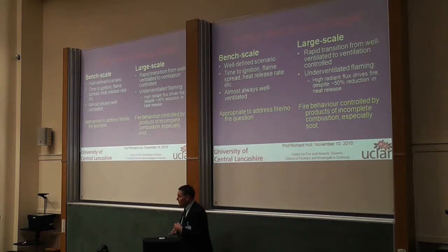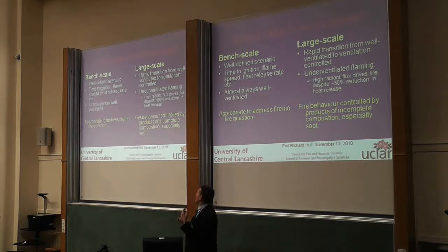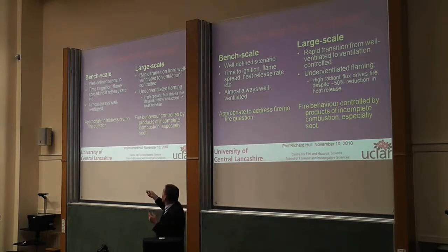So, in terms of whether the input data is fit for purpose, I would define bench scale tests, the sort of things that you were talking about, not large scale configurations. The fire propagation apparatus is better than most bench scale tests, in the sense that most bench scale tests look at a well-defined, well-ventilated fire scenario. They're very suitable for looking at the time to ignition, perhaps the early flame spread and the heat release, but they're almost always well-ventilated, and they're very good for addressing the fire or no fire question. Are you going to get ignition? Are you not going to get ignition?